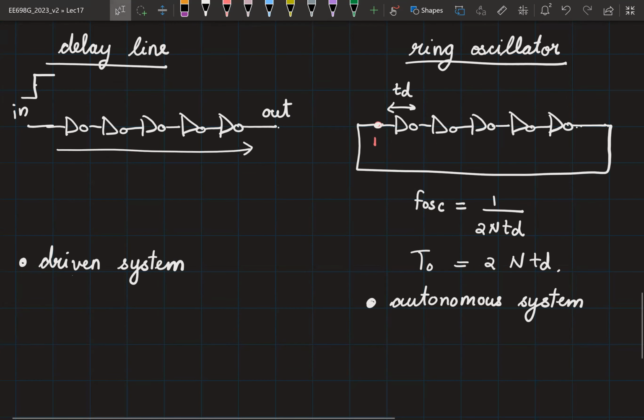Okay, so now let me look at its output. Say I looked at its output for 10 minutes today. I looked at its output for 10 minutes tomorrow. Assume that the system is continuously running. What comments can you make about the power of the jitter here, or the RMS of the jitter? Does it change from today to tomorrow? The RMS has to be the same, right? What would be the value of RMS?